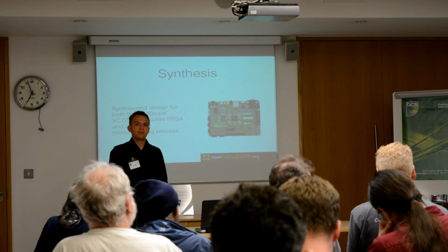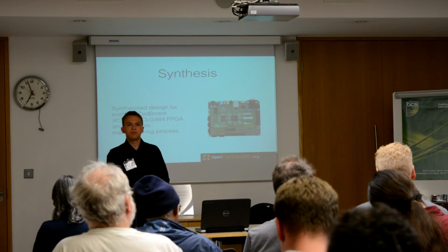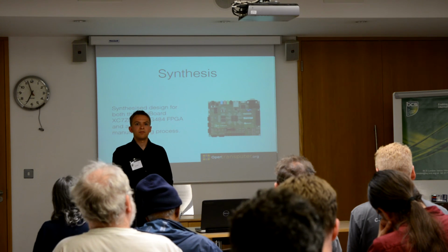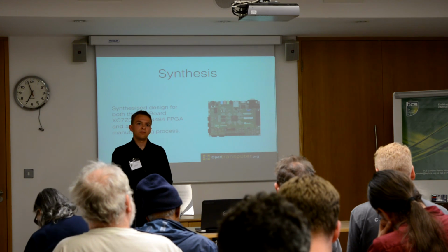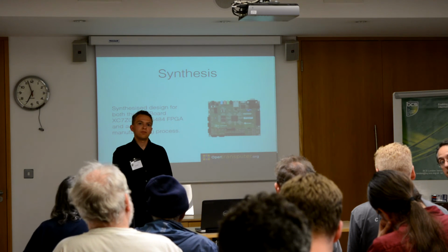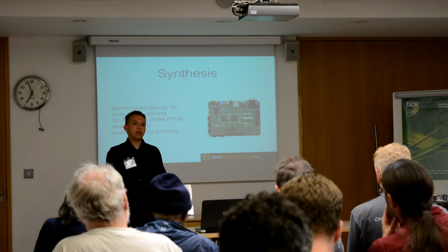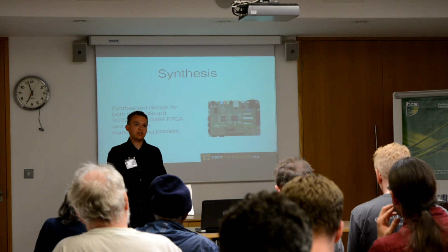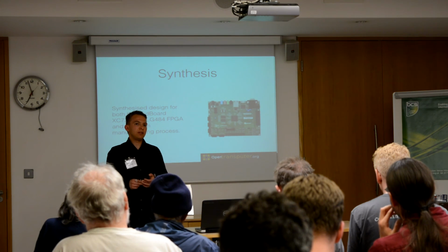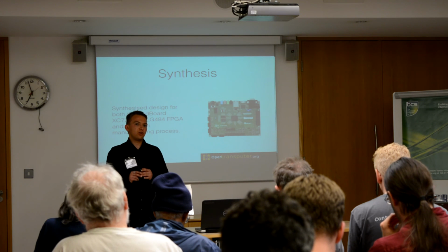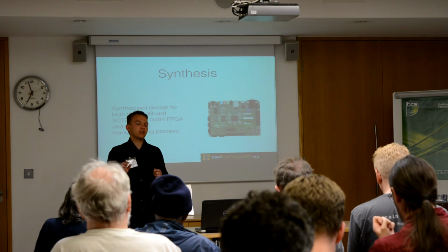So you mentioned that one of the benefits of your design is that you improve process switch time by using shadow registers. Is there a limit to the number of sets of shadow registers you can have, or what do you do when you hit that? Theoretically, you can have as many registers as you like. I think at the moment we keep it quite low. I'm not quite sure how many sets there are, but I think there's only one at the moment.